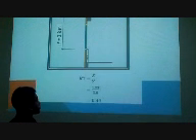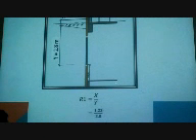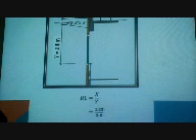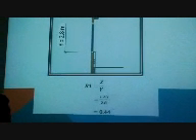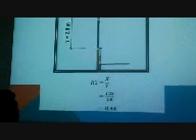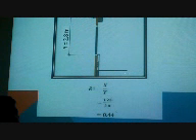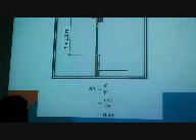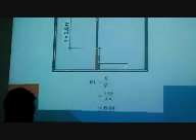This is how we find the R1, the ratio of shading and the window, x divided by y. You can see the shading x is equal to 1.23, and the distance between the shading to the lower part of the window is 2.8. Therefore, x divided by y is equal to 0.44.